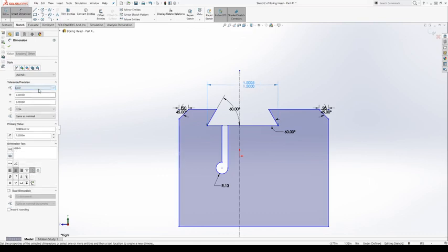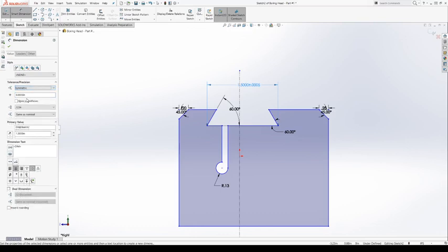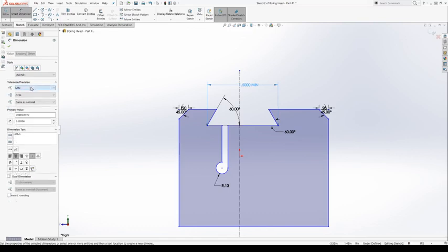Limits, right? Pretty self-explanatory. Same tolerance. Tolerancing, as far as how it happens in the property manager, doesn't change, but what does change is how it's displayed, and that's it. Still the same tolerance. Symmetric, that's our unilateral tolerance, so that's a plus or minus 1/2, right? Got to do that. Can throw a parentheses if we want. Doesn't really matter. Min or max, right?